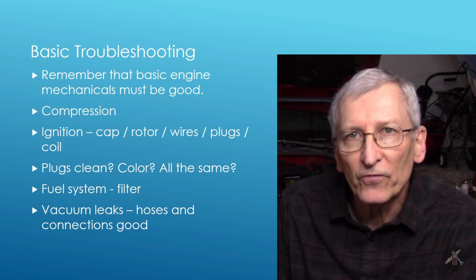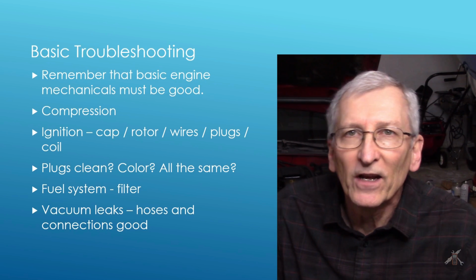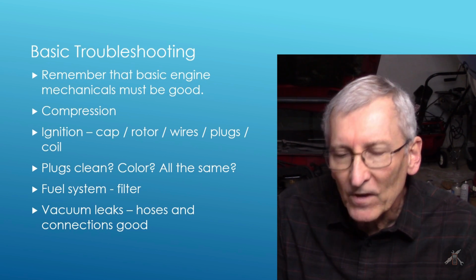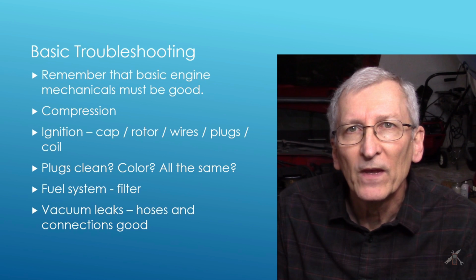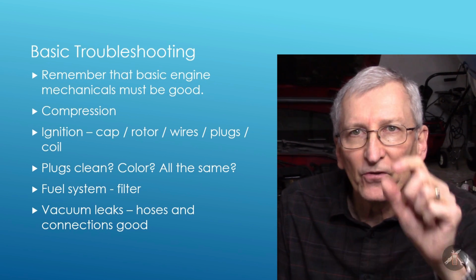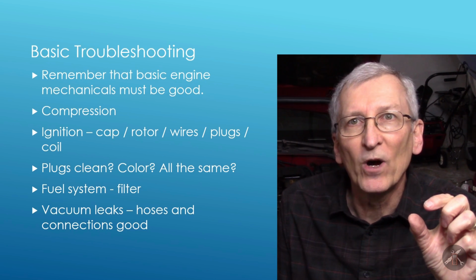The thing I watched for is the bearing clearance in the shaft. I did a check with a dial indicator, as I recall, to make sure that the bushings aren't worn. If the bushings are worn, typically the sign of that is your timing mark on the balancer. When you go to check timing, it'll start getting real wide.